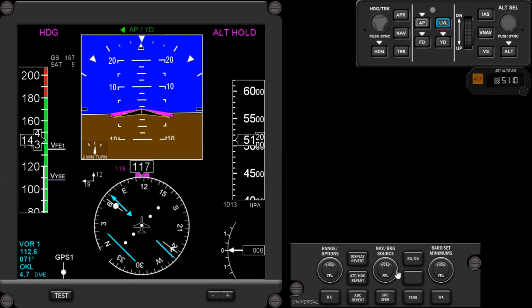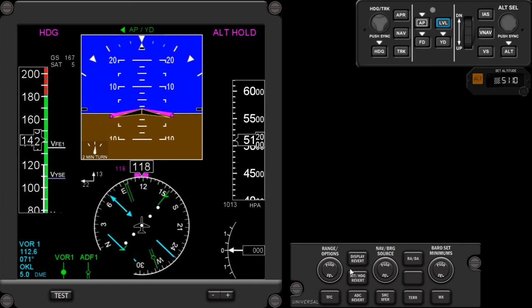And there is the GPS showing towards the GPS waypoints. So let's have VOR1 here, and on the other RMI we can have maybe ADF1. So pretty big choice of things to display at once. Now it becomes a little bit cluttered with this many things displayed, but if you need this for some reason, why not? I will turn them off.